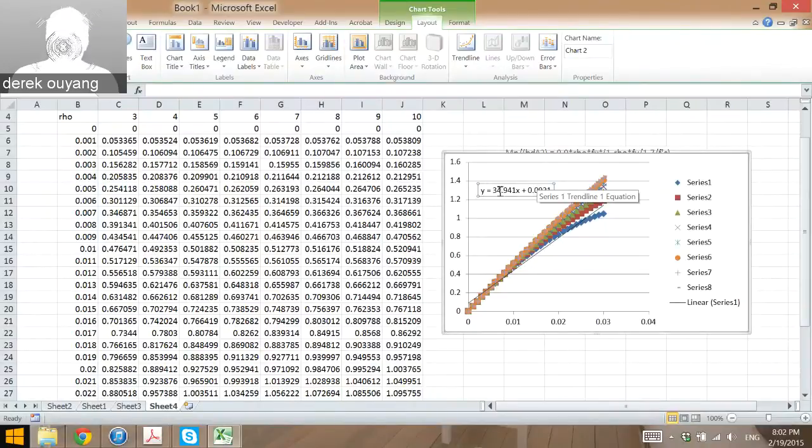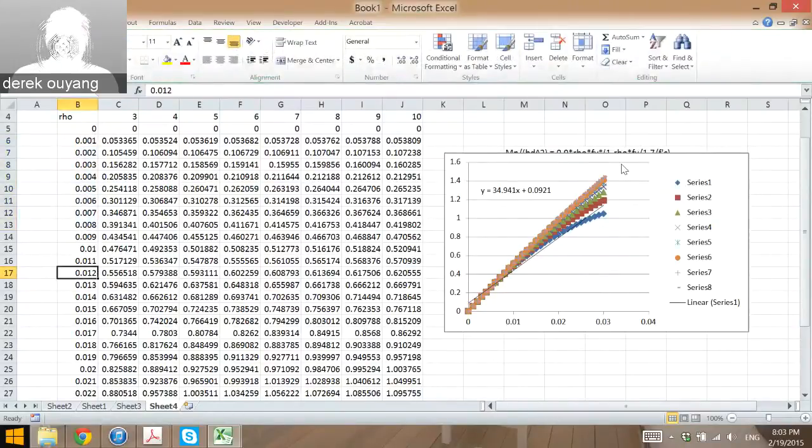Because this is a linear function, which is very easy to plot in Excel, you just throw in your values of bd squared, which are maybe architectural constraints, and then you put in an Mn, and then it immediately tells you the rho, and you can get a sense of whether this makes sense as a design or not, right? So you can build these any way you want and for whatever purpose you want, but just see the value: you iterate on every single possible combination of a variable, you get the scatter plot, you create a trend line, and that becomes an easy shortcut for you. Okay.